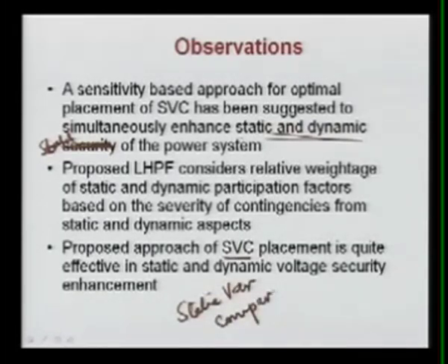Basically, we are changing the impedance, and it is a shunt device compensator. Another shunt device that people are discussing very popularly nowadays is the STATCOM. Function-wise it is similar to the static var compensator or SVC, but the STATCOM gives better performance than the SVC at several locations. They are very important, but the STATCOM is very expensive compared to your SVC.